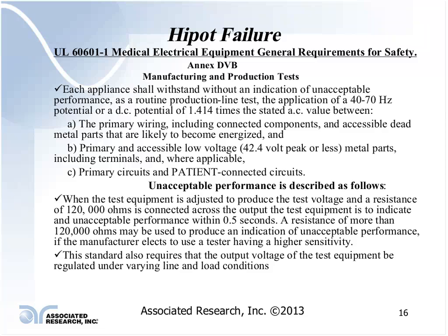So all of these circuits are in fact tested whenever you are performing a Hipot test. So it may be not only requiring one test, but you may be doing 2 or 3 tests to make sure that you're testing all of these circuits, and they may be done at different potentials.